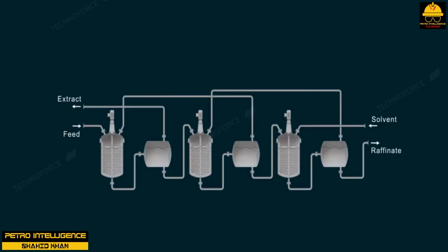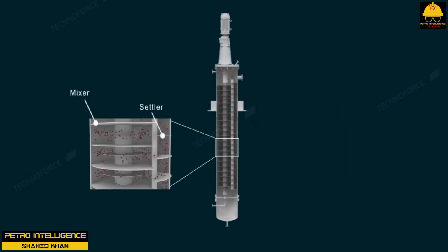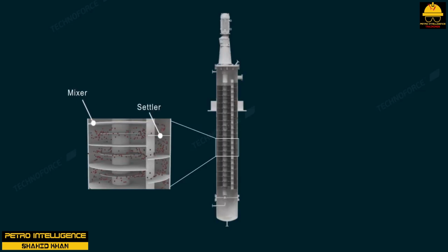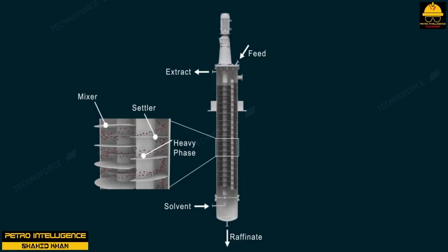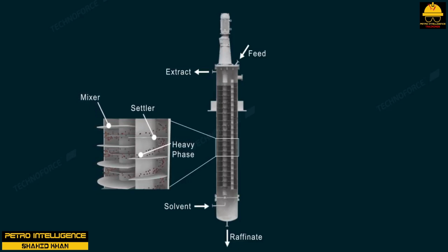Such a process could be converted to continuous operations by continuously adding the feed and solvent and continuously withdrawing the raffinate and extract. For such a process to be successful, some means of mixing or contacting the materials must be provided while still allowing ample space for the raffinate and extract to layer out. Many simple yet ingenious means have been employed for this purpose. Most frequently, a single-stage device as described will not provide a perfect separation, and the raffinate must be contacted again with more solvent to complete the removal of all solutes. This problem leads to the concept of the multi-stage operation.